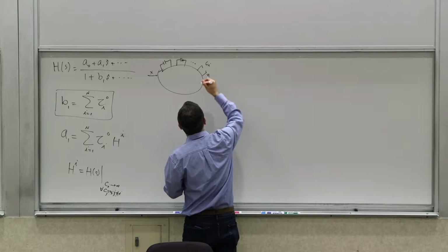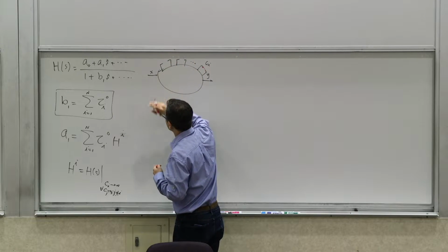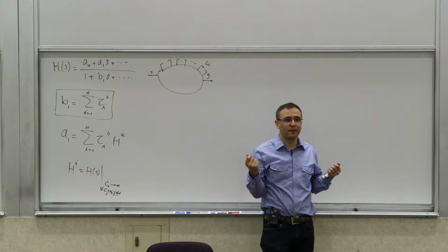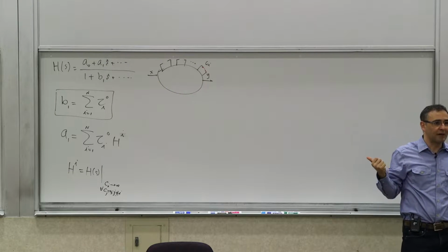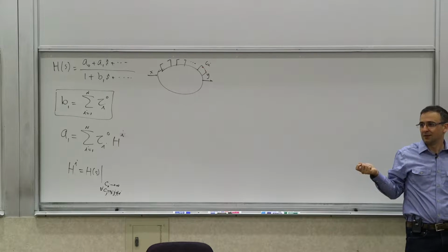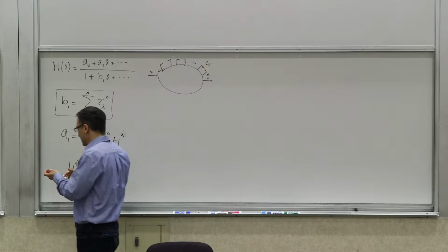In this case, for a capacitor, it would be a short circuit, and everything else would become open circuit because everything is zero valued. And you look at the ratio of the output to the input. It's a low frequency calculation because now all the energy storage elements are either short circuited or open circuited. Right? So it becomes a low frequency calculation. And that was the a's.